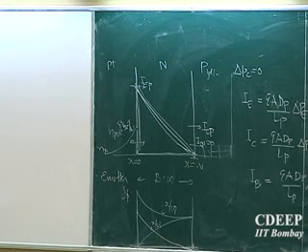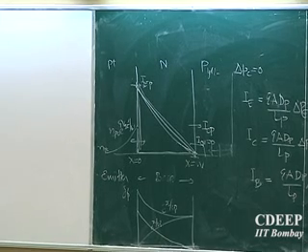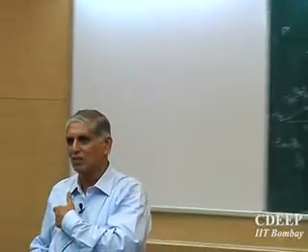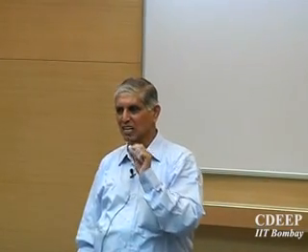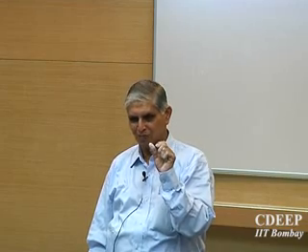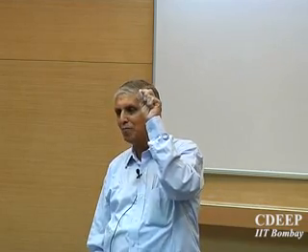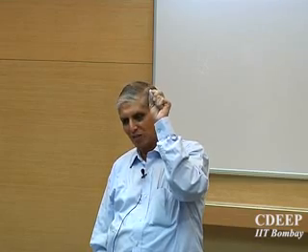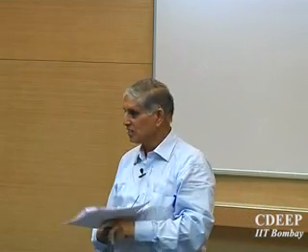But I just taught you the PN junction, so I ask again: if I apply positive 1000 volts, VB becomes positive 1000, what will the device do? It's a heavy injection case. What did I say? It becomes like a resistor, a high injection case. It will push a hell of a lot of carriers across, but still VB will become no more than 1 volt. Is that correct? The rest of the voltage will go as IR drops. IR drops. Is this fact correct?